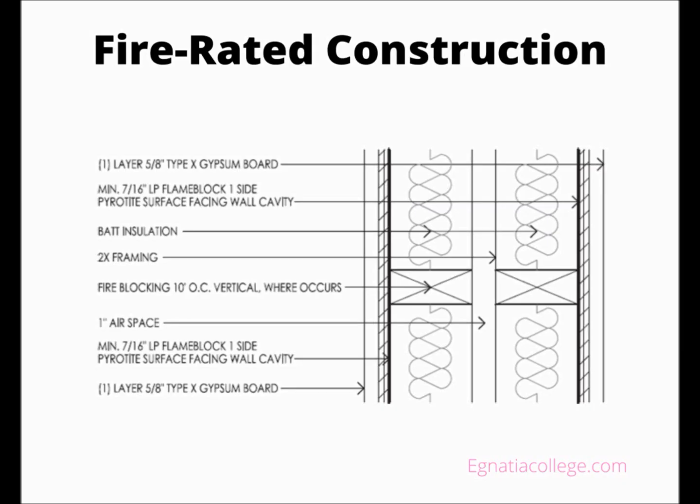The most obvious way in which a wall, floor, ceiling, or roof can slow the spread of fire is by having a fire-resistant surface. Plaster and gypsum wallboard are fire-resistant materials. They do not burn, and they do not easily transmit the heat of fire to the framing members on the other side. Unfortunately, standard gypsum wallboard breaks down and crumbles in very high heat.